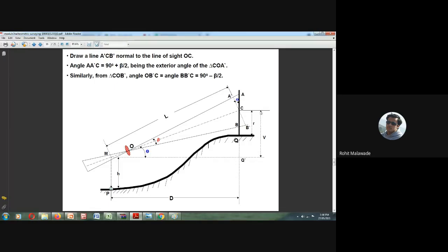If we do minus v, we get the height till this, but we want the elevation of point q, so v minus r. If we do minus r, we get this particular height q from the point p. So we will be using the equation: elevation of point p plus h minus v minus r. Is it clear? Yes, sir.